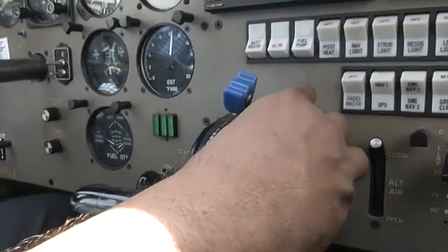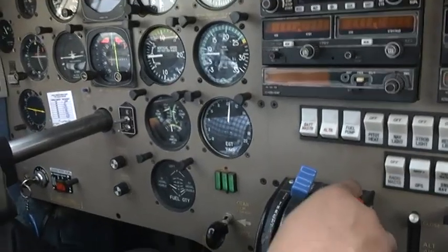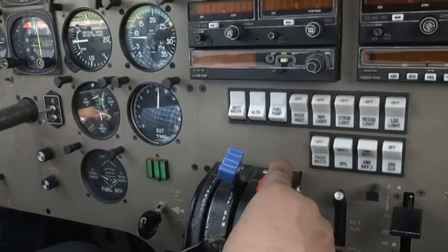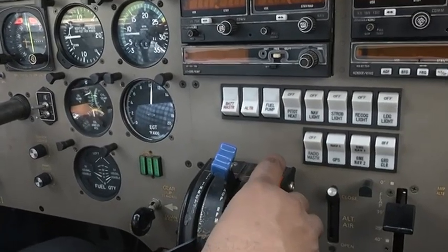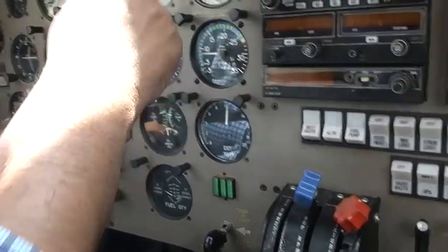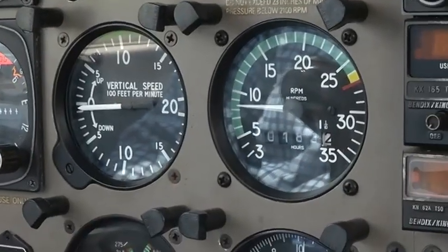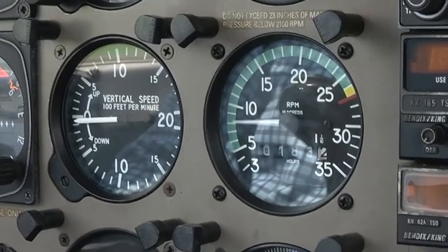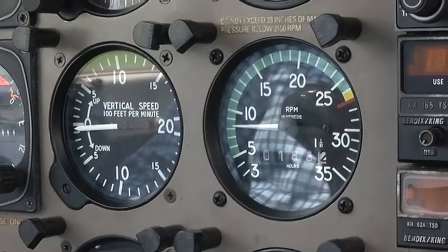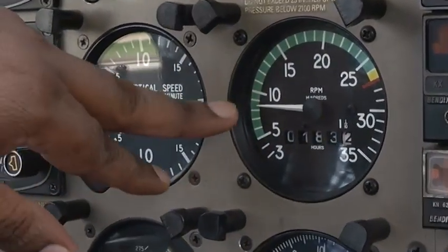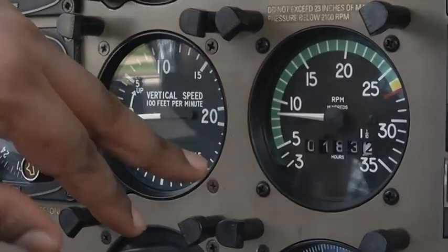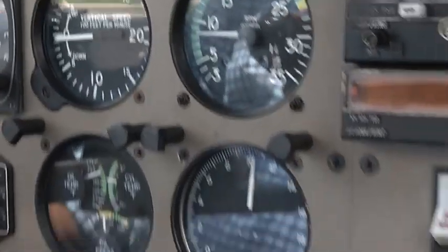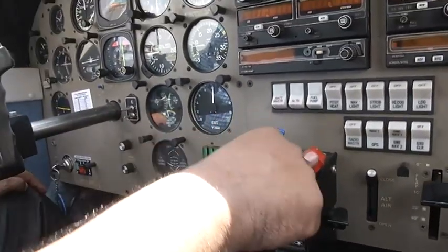the mixture also. Now to check the mixture, I will put the mixture control from rich position to the lean position gradually, and the increase in RPM should not be more than 20-25. So just see that I'm gradually moving the mixture control lever from rich position to the lean position, and you can see there is an increase in RPM of around 25. I have again moved the mixture control lever back to rich position, just in order to ensure that the